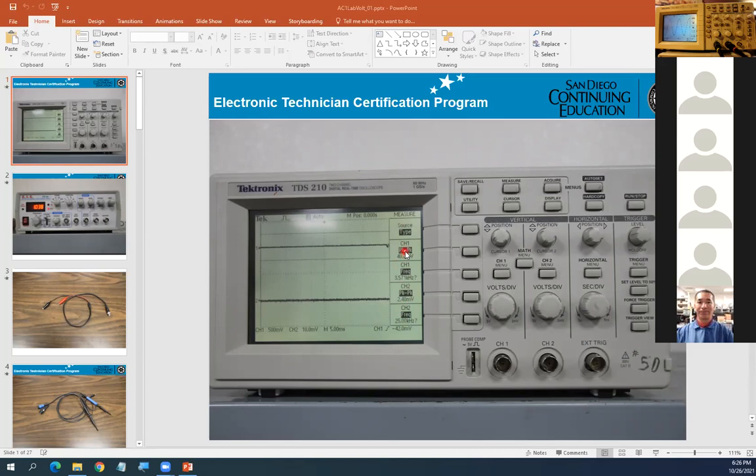Which window for input channel 1? Which one for channel 2? That's the first thing you must set. The second thing, you must set for channel 1 what you want to measure. Is it the peak to peak, or the frequency, or whatever? And for the second one, same thing: what you want to measure. And that also applies to channel 2.